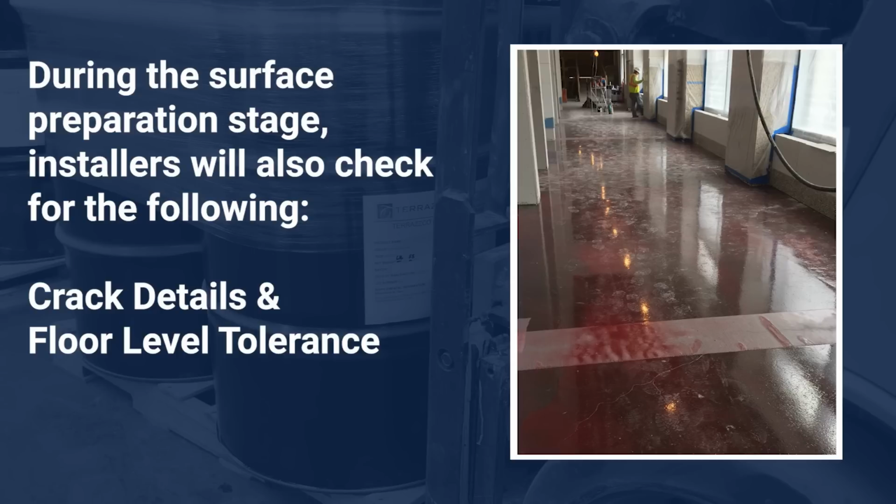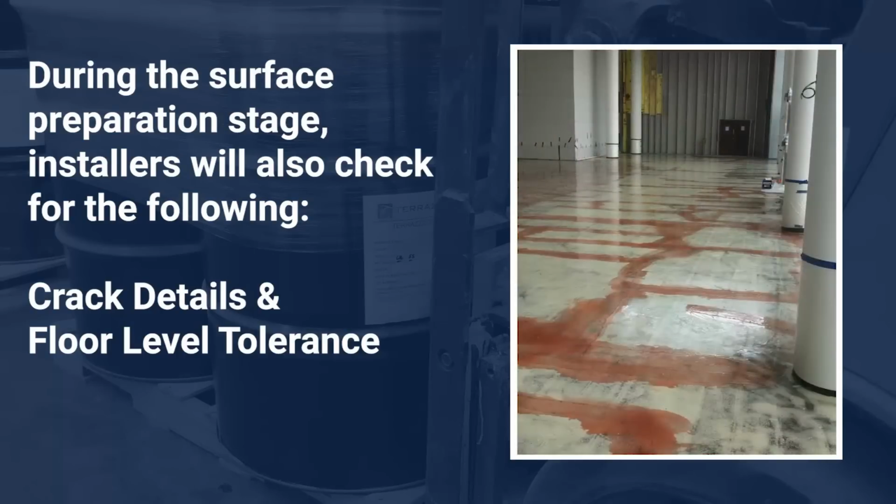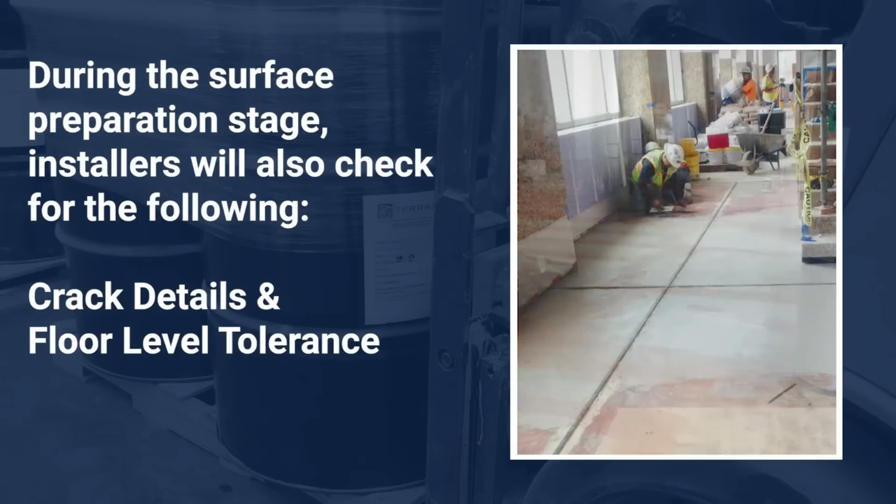Installers will also check to make sure that the floors are level, as well as look for crack details. Flexible epoxy can fill in cracks, which helps prevent substrate cracks from transmitting to the terrazzo floor during the entire floor's life cycle.